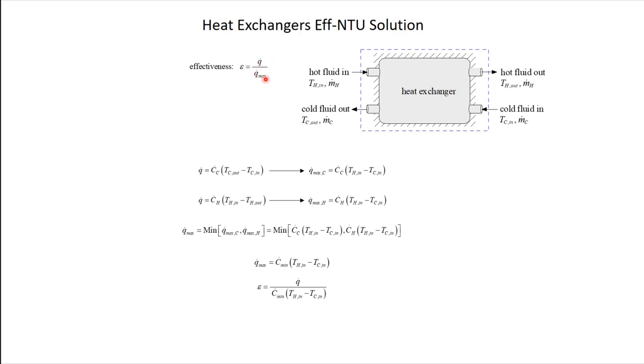So where does this Q dot max come from? Usually, if you remember from thermo or really anything, the trickiness of understanding an efficiency definition is understanding this limiting behavior. So what is Q dot max here? What is the best it could do? And the way you think about Q dot max for a heat exchanger is you go to the energy balances on the two fluids. So here's an energy balance on the cold fluid.